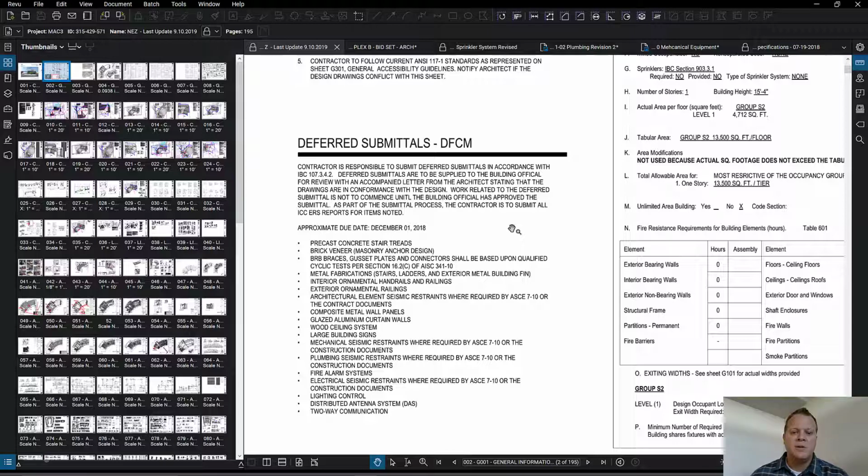Well, why would the building official need to see this? If they're talking about submittals, submittals almost always go to the designer. Well, that's not true. You could have a municipality that has civil or other infrastructure type submittals like asphalt or water line, and all those types of submittals often go to different jurisdictional parts of the city or county, whatever. But the vast majority of submittals really just go between the design team and the general contractor. Sometimes the client's involved, sometimes other parties, but the general rule is submittals are going between the contractor and the designer.